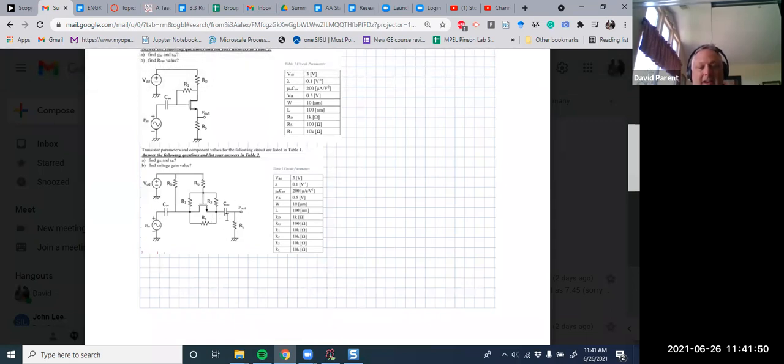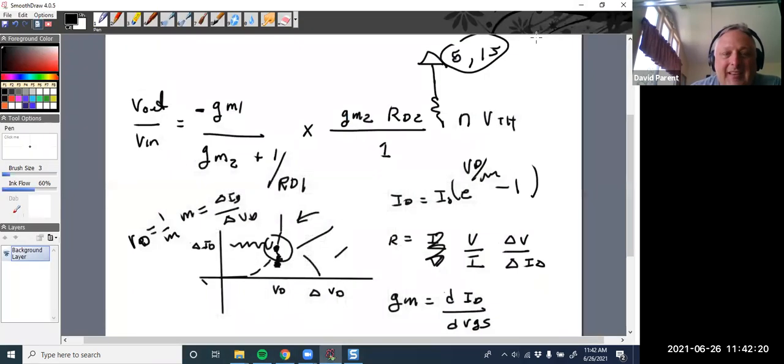Now, yeah, if those capacitances aren't exactly infinite, and nothing is truly DC, it's really close to DC. So maybe there's a little bit of connection there, or that capacitance has a leakage. A real capacitor has an inductance and this leakage term.